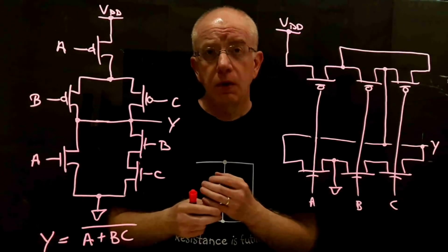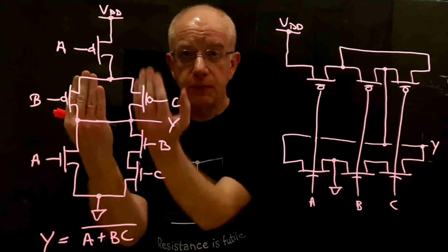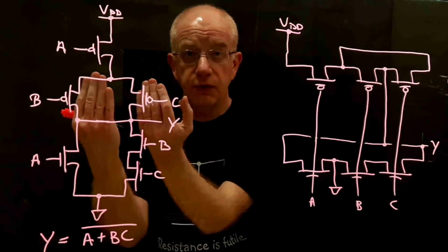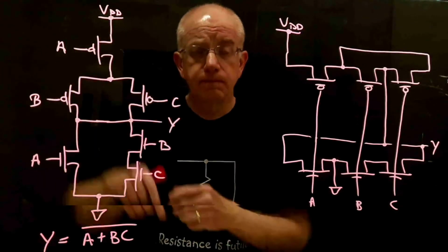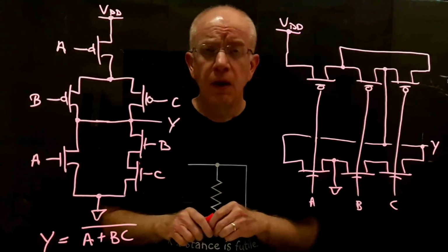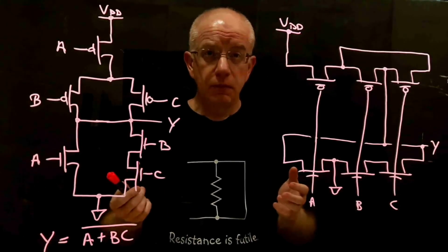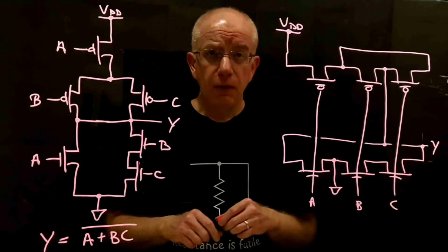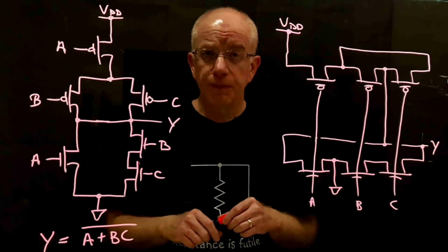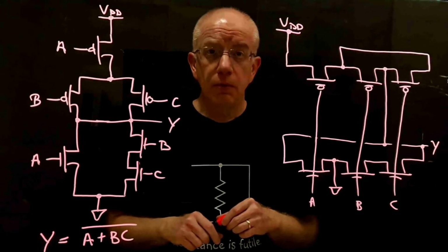That will match those two devices better than if I have the A device and the B device next to each other like this, not physically interleaved. So these so-called schematic-driven layout tools don't typically produce very good layout at the end of the day. But if you do the schematic with the layout in mind, you'll achieve much better results.